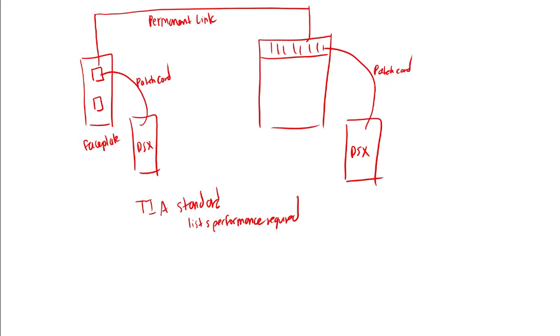And so a few things that we need to know: the link's maximum length is 90 meters plus 10 meters of patch cords.